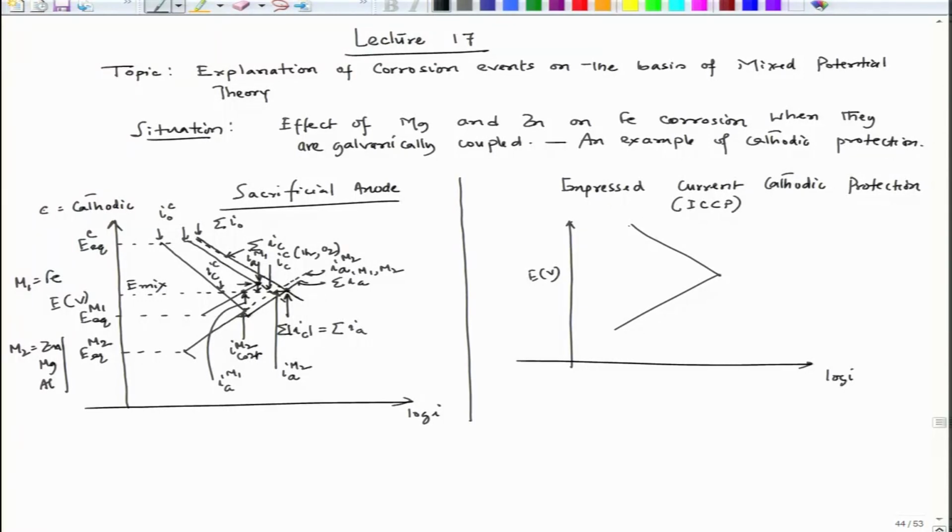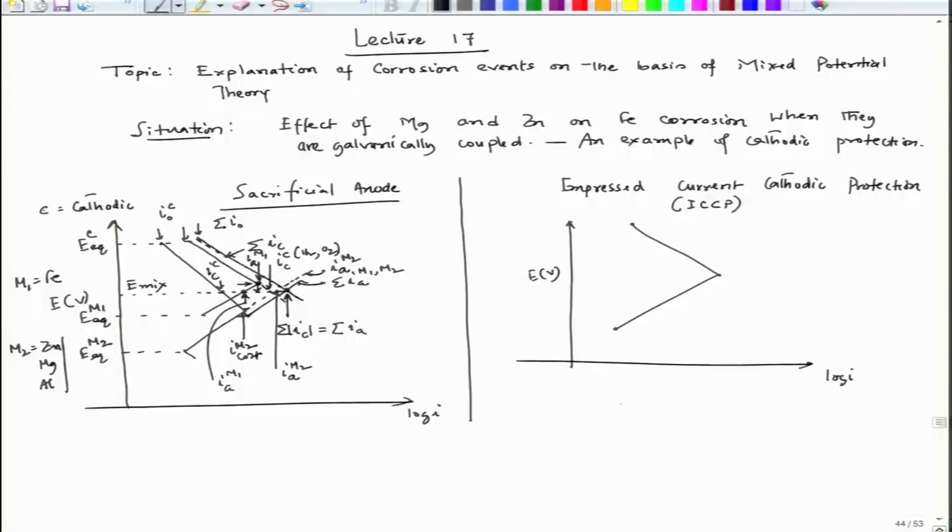Rather, I would have an electrode which will be just used to supply negative current, just used to have a completion of the circuit. So, what we are doing, let us say this is the metal object which is to be protected in an electrolyte, and that electrolyte could be soil solution or sea water.